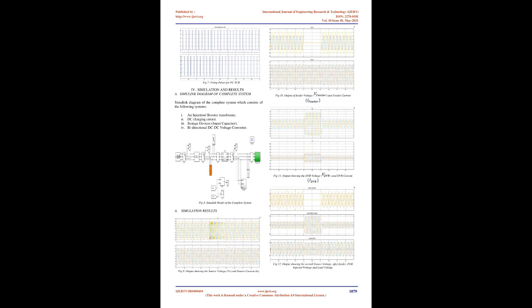Thus, the flow of current will be blocked once the AC current crosses the zero limit. When the thyristors are fired at the crest of the voltage, the current flow in the thyristors is the most. The current flowing in the reactor can be varied from the extreme to zero by varying the firing delay angle with respect to the peak of the voltage applied in each half cycle.